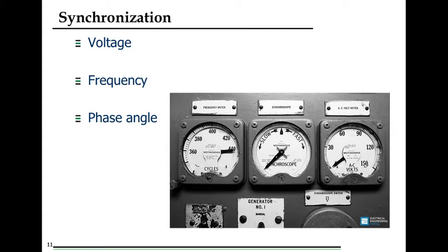So when we are trying to synchronize our generator to grid, this means we are trying for active power to go from generator to grid, so that our equipment functions as a generator. If there is a reverse direction of flow, means if the active power flows from grid to generator, this will be the motoring action. And if we keep the frequency same, suppose the grid frequency is 50 Hz and our generator frequency is 50 Hz, this is a floating condition and no flow of power will take place.